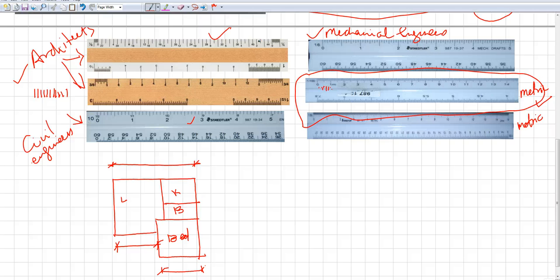And obviously it doesn't make sense making a drawing at full scale, especially if it's as big as a house. So that's when I use these scales to scale my drawing down, but at the same time it's still to the specific scale. So if I use 1:8, the one that you see over here, what that corresponds to is 1 foot on your side corresponds to 1/8 inch on your drawing.